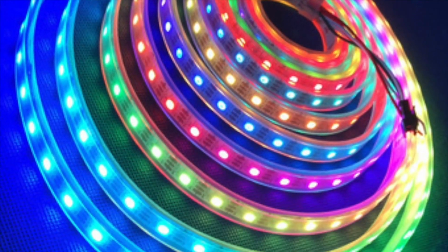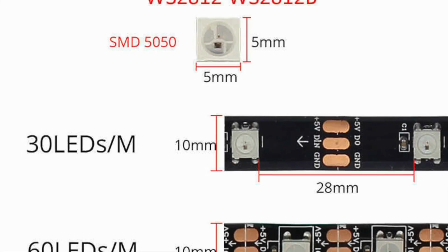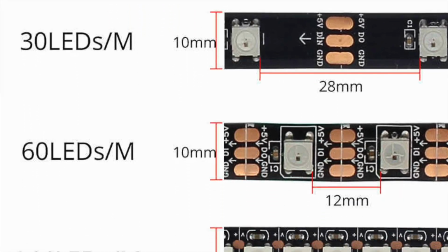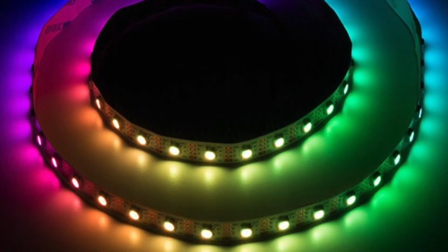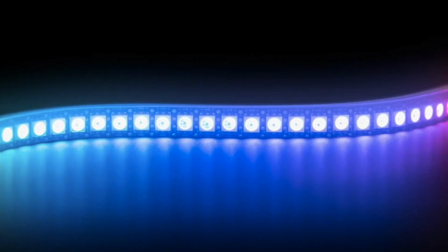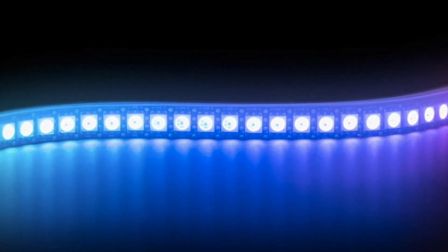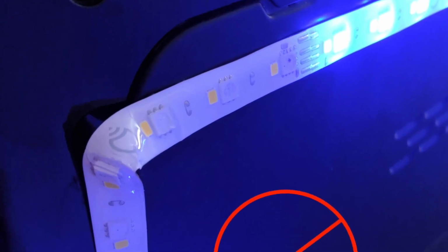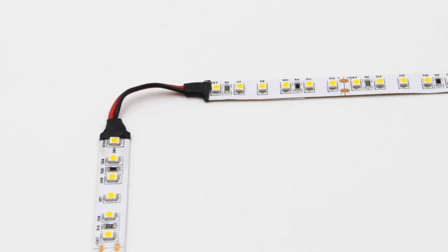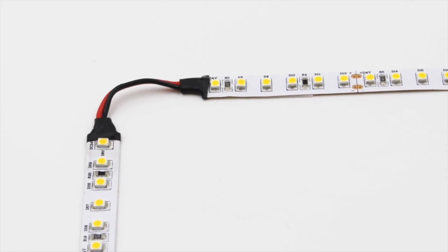LED strip, the LED workhorse. Strip comes in densities from 30 LEDs per meter to 144. Higher density strips require more power. Note that LED strip is easily damaged if you don't take care when installing it. It's best to not bend or crease LED strip, so if you take it around a corner, it's best to cut the strip and solder some jumper wires between the two strips.